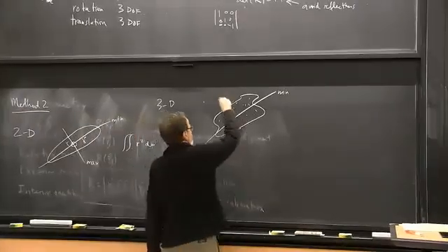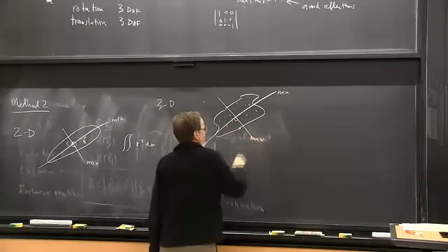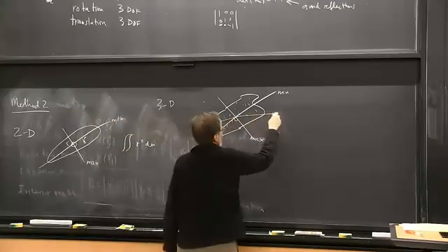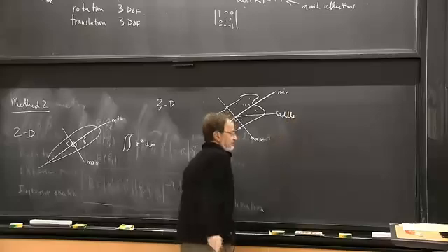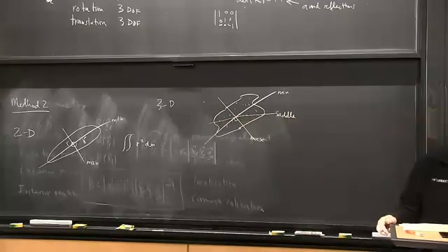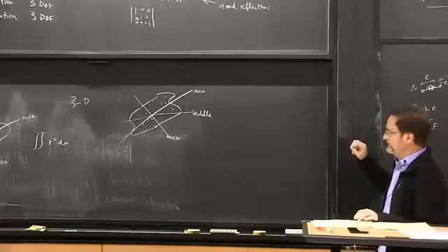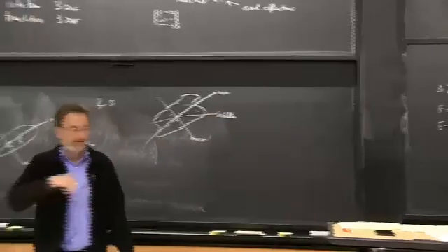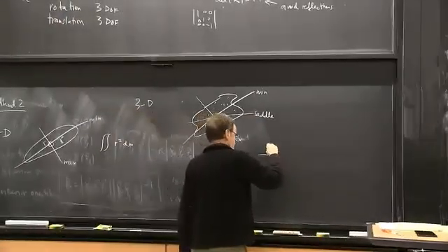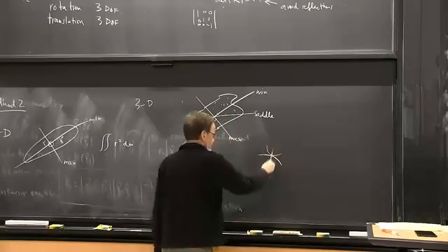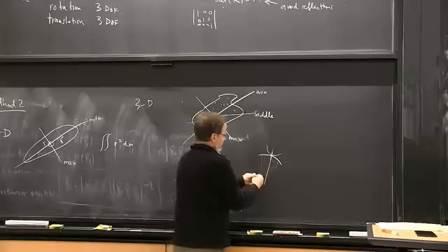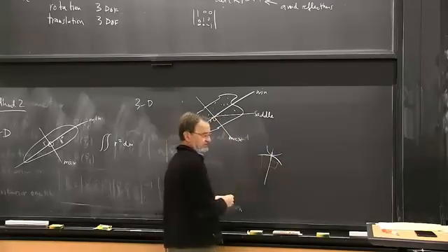And in 3D, we're then also going to find that there's a perpendicular axis that has maximum inertia. And the difference about 3D is that there's a third axis, which is a saddle point. So if you move the axis in one direction, the inertia gets bigger in a quadratic way. And if you move it in another direction at right angles, the inertia gets smaller in a quadratic way. It's kind of hard to draw, but here's the idea of the saddle point axis. If you move it in this direction, the inertia goes down. Same on this side. But if you move it at right angles, then the inertia goes up quadratically.